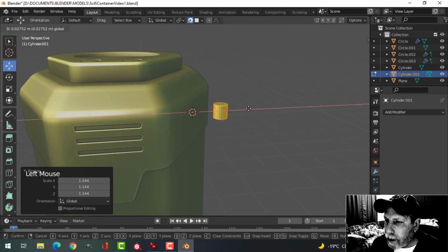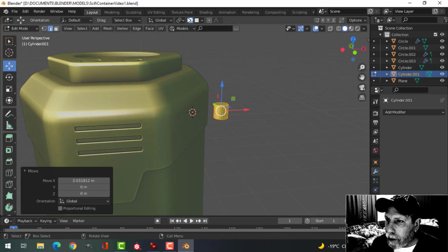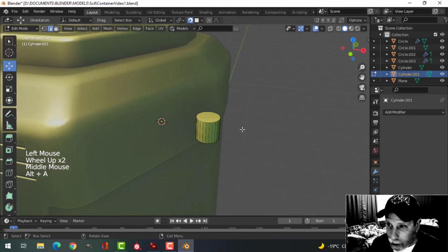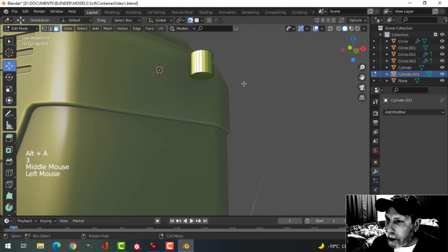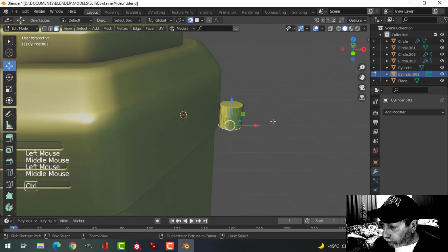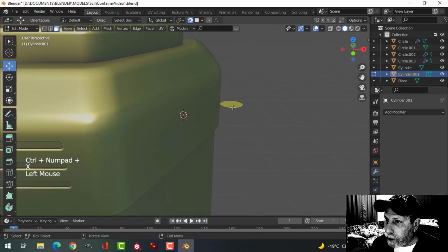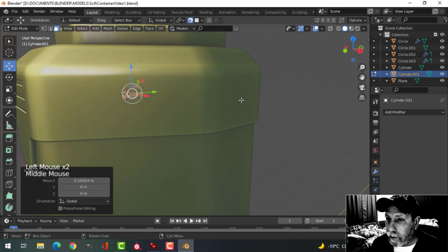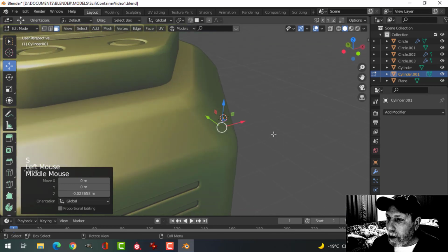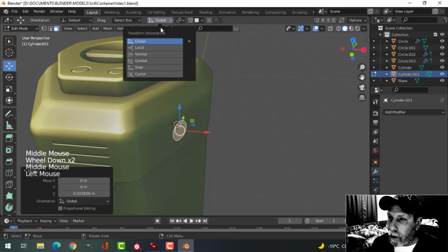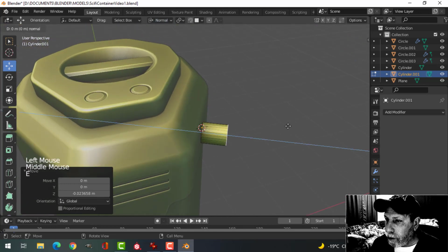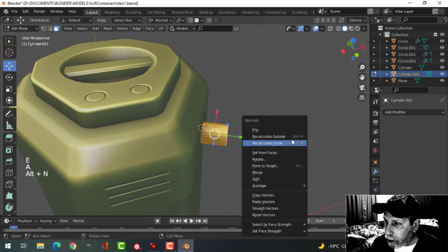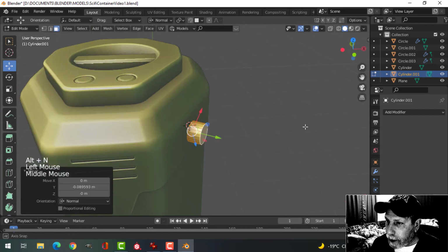It doesn't snap that good. I might be doing something wrong. So what I actually tend to do is just to take that and just use one face, and maybe that's what I'm supposed to be doing anyhow. That's what I want to do. All right, turn that off. And just move this down and scale it. You'll see how well this works. I'm going to switch over to normal. I'm going to extrude out. Make sure my polys are in the right way. And push that in.